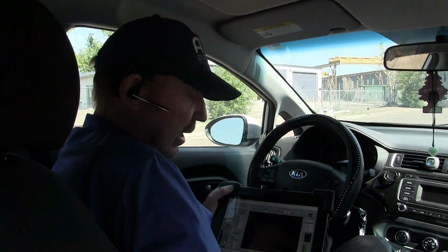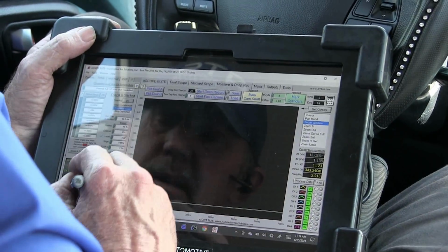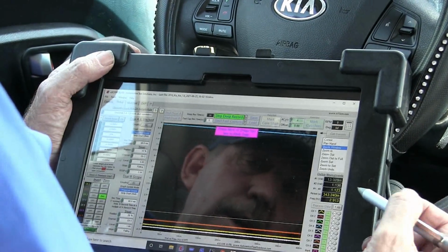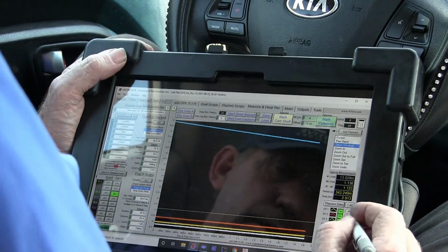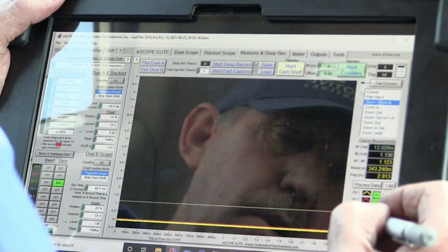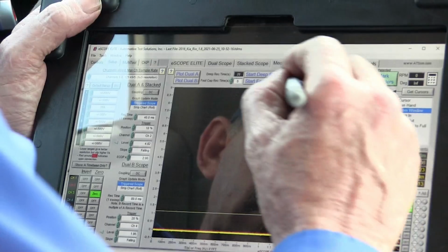Okay, I have the scope connected. Let's go ahead and set the scope up. On channel 3 I have an amp clamp. I want to zero it. We want to come over and get the data. But I want to do one thing first. I want to shut all the rest of the data off for right now. I want to focus on the signal, which is yellow, and the 5 volts, which is on channel 2.